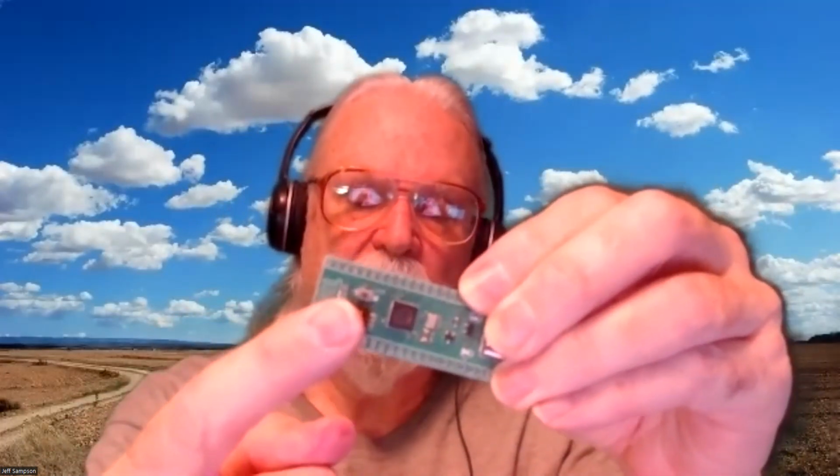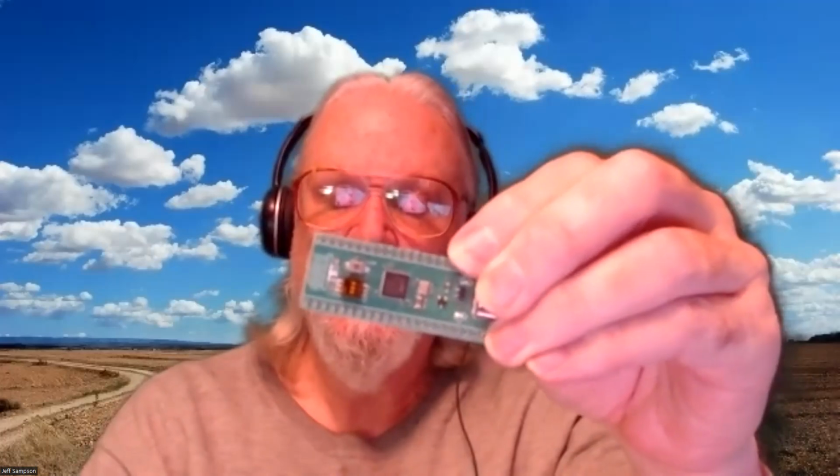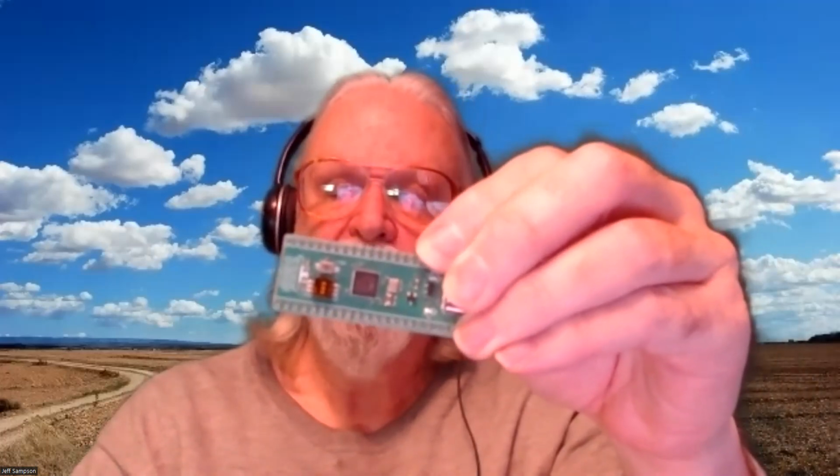So I'm thinking if I just solder a wire and run it out to a push button somewhere, I can just push that, and I could bring the reset and a push button out, just for convenience on a breadboard, so I could do that without having to move the jumper wires around. Now, on the other hand, if you're going to put it inside of a box, you can put your push buttons or switches on the outside of the box. So if it craps out on you, you could walk up and just externally do the combination of buttons, and that'll put it in a bootload mode for you.